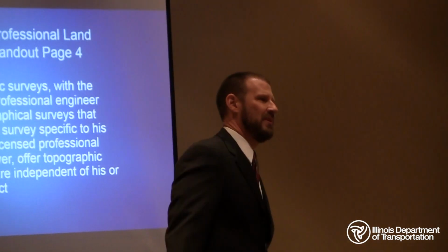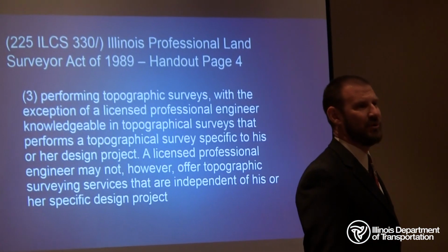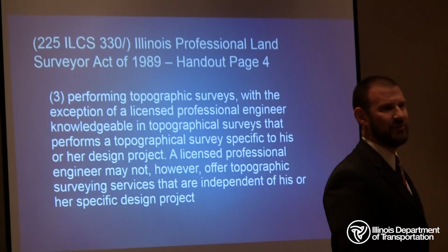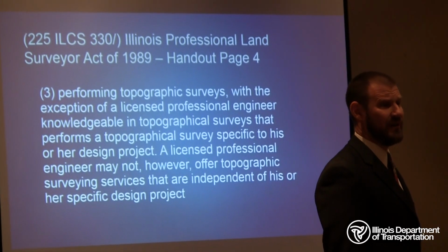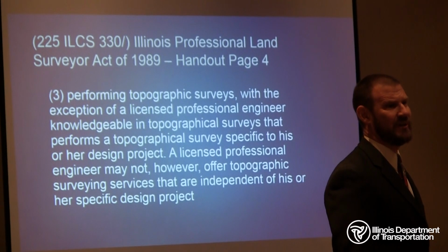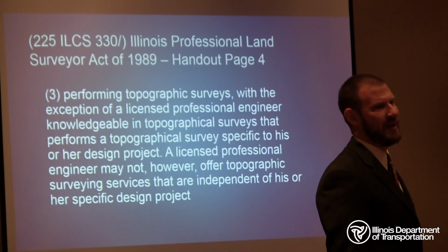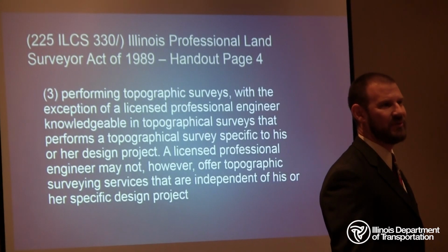Just want to point out from this that topographic surveys that are going to be used for design purposes need to be done under the direct supervision of a surveyor. Engineers can do it, but it is specifically for the project that they're going to be working on. Basically, just kind of pointing this out as we explore measuring technologies, please involve your district surveyors.